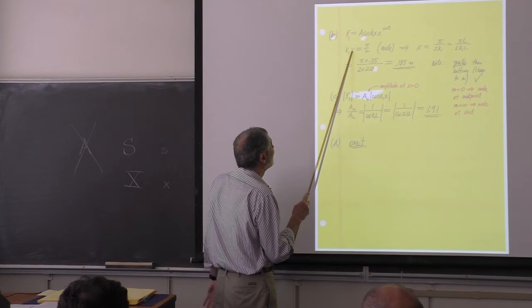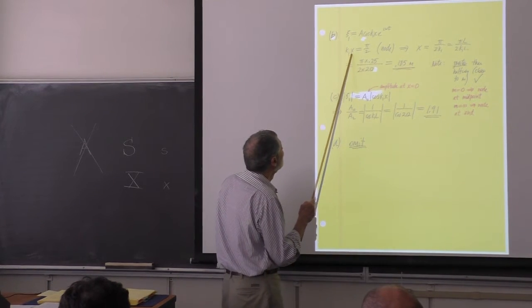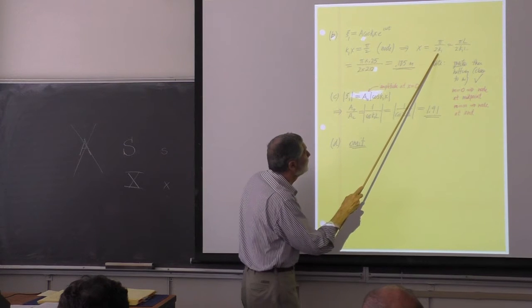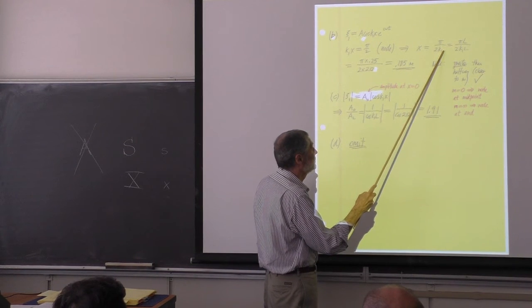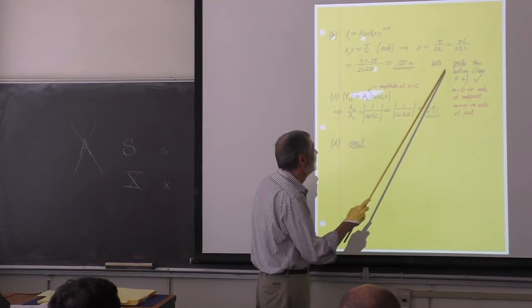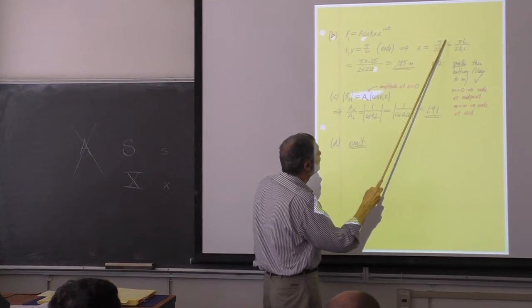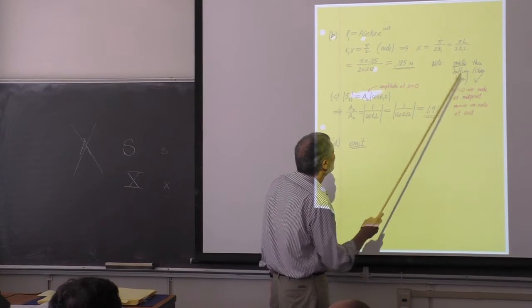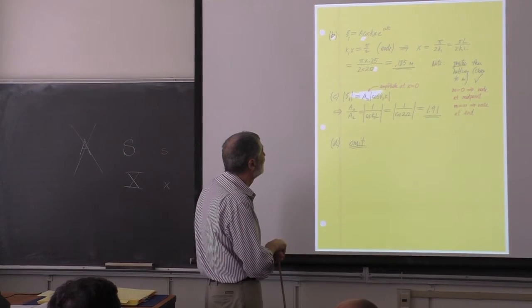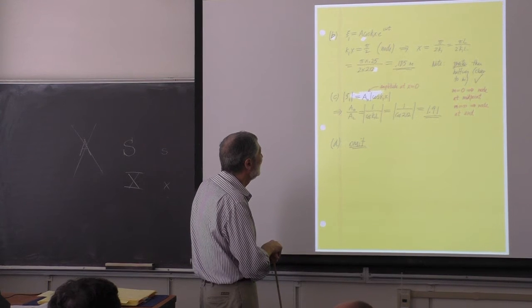And we're after x. Well, we know x will be given by this. We know k1. Well, we know k1L. It's easier just here, because that's what we solved for numerically. Whatever it was, 2.12. So I'm going to multiply numerator and denominator by L to get my nice dimensionless quantity here, plug the numbers in, and I get 0.185 meters.